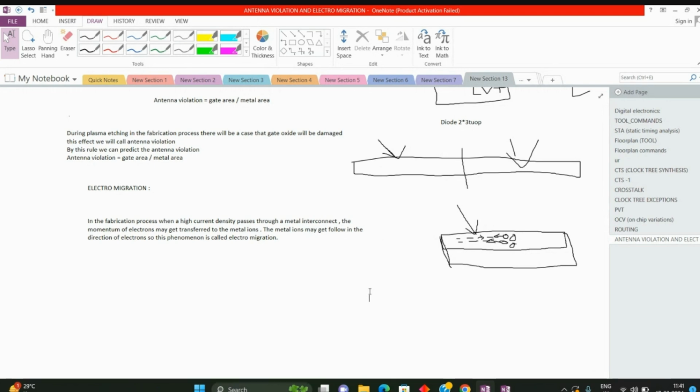Suppose with those methods maybe you're having some 1,000 picoseconds of violation. Suppose you have applied some path grouping over there and your timing came to 300 picoseconds of violation. So 700 picoseconds of violation got reduced without changing any netlist. Maybe if you size it to some LVT or HVT, your timing will come to zero. But still, without changing the netlist, you have recovered 700 picoseconds of violation. So in the PNR, for simple blocks, with those commands only, your timing will get fixed. Only for complex blocks, it may not get fixed.